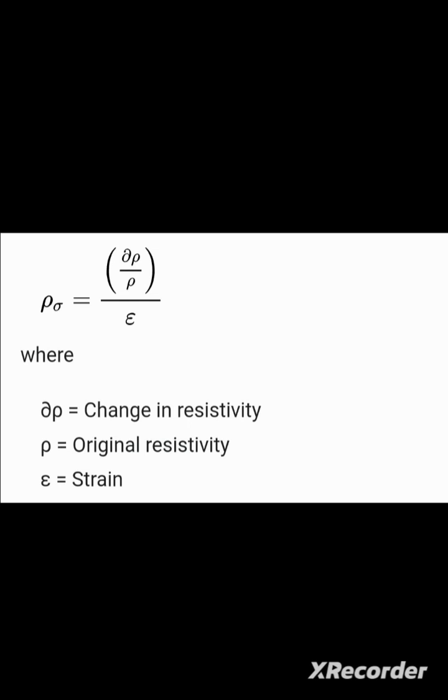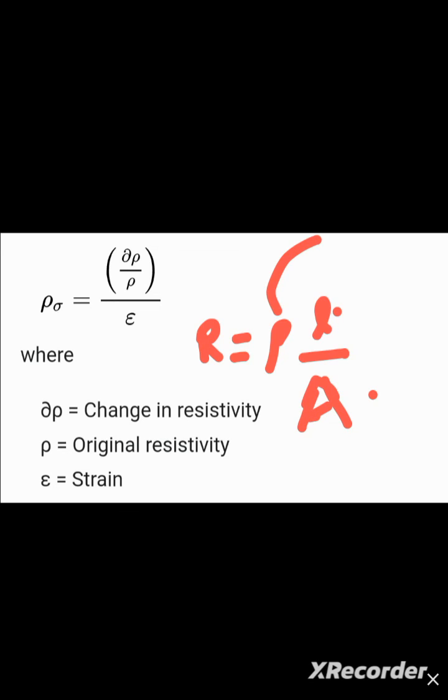So in that case, you have a thin diaphragm that vibrates due to applied load, and because of that vibration there is a change in the resistivity of that semiconductor resistor, and therefore its resistance R gets changed. Remember, R is rho L over A. So here your dimensions L and A are constant, but your resistivity is getting changed. So that's your piezoresistive effect.